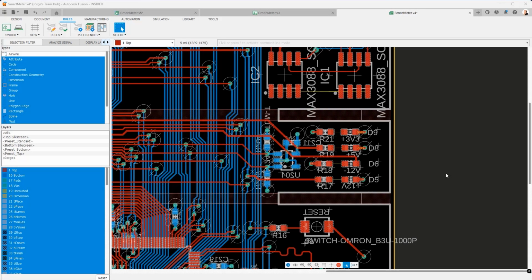In this example, I want to illustrate the use of a component scope. So how does this work? Let's say I have these diodes, and I want to make sure that any traces that are connected to these diodes and part of this group will have the same width. The first thing we have to do is create our persistent group. I want to make sure I get the air wires as well, so I'm going to hit Control, select. That way I include air wires. I'm now going to form my selection.